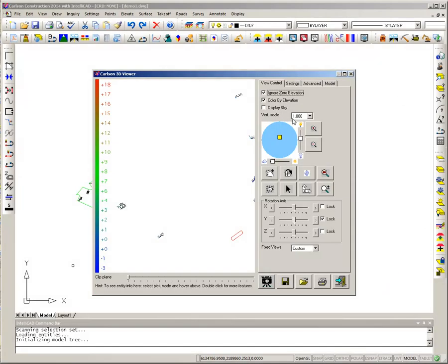And you can see it looked like everything was at 0, but there are some things with some funky elevations in here. Some stuff's at -3. And some stuff's at 18 elevation. And if you remember, our existing was all between 803 and 850 or so. So I have some problems here. Things looked like they're at 0, but they actually have some elevation.